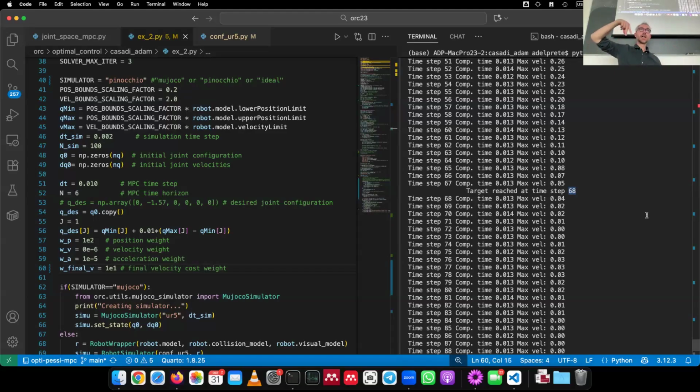Think of a humanoid robot walking: if it's a cyclic walking, the set of states that the robot goes through defines a control invariant set. But none of those states has zero velocities. Zero velocity is just the easiest example, but it doesn't need to be zero velocity to be control invariant.